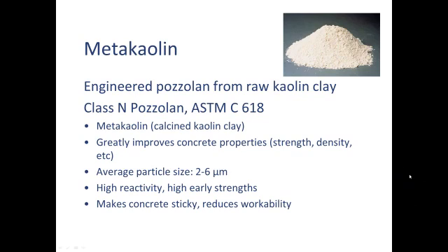So metakaolin: meta is Greek for change, and kaolin is a type of clay. So they change the clay. You'd never ever put kaolin clay in concrete. It would weaken your concrete. But when you use calcined clay, it's chemically changed, it's now chemically reactive. It gives you a very highly reactive, very small particle pozzolan that can actually give you higher early strengths. You can get higher 3-day strengths using metakaolin than you would if you didn't use pozzolans at all. So this is one of the few pozzolans that actually boosts your early strength.